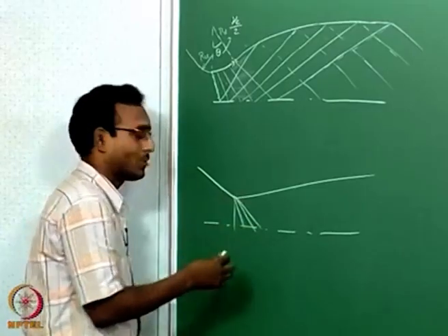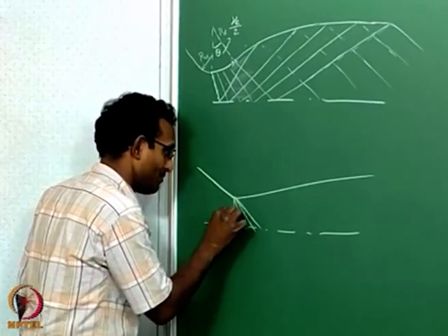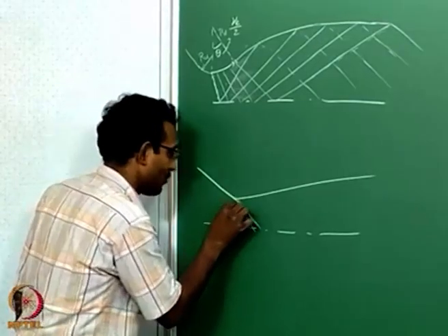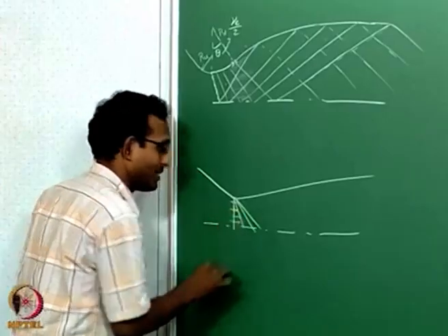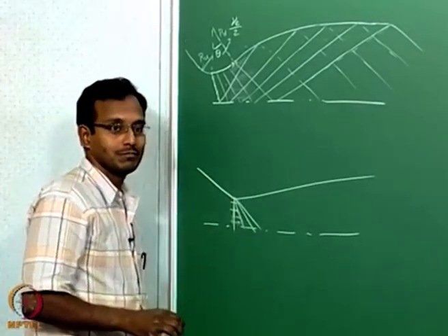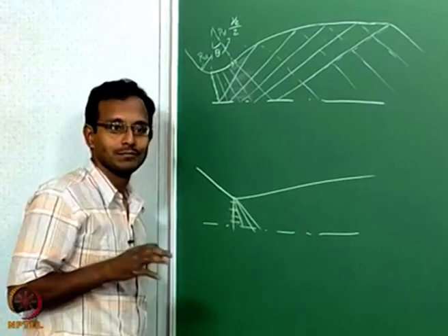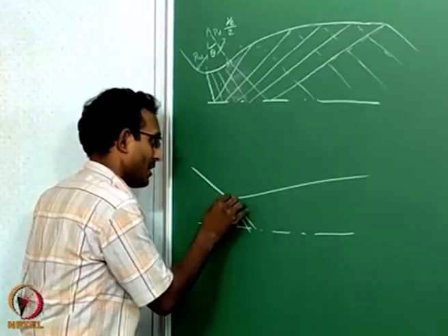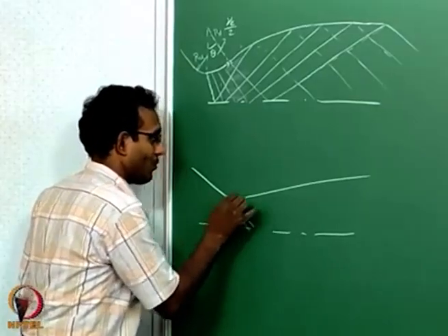Point expansion we already talked about, right. I am going to assume the very first line to be a straight vertical characteristic, and I am going to assume flow here is exactly parallel to my symmetry line, and my Mach number is 1. It is not a very good assumption, but it is the only thing I can do right now. So I will assume it that way, okay. And from there I know the final angle of the wall locally.